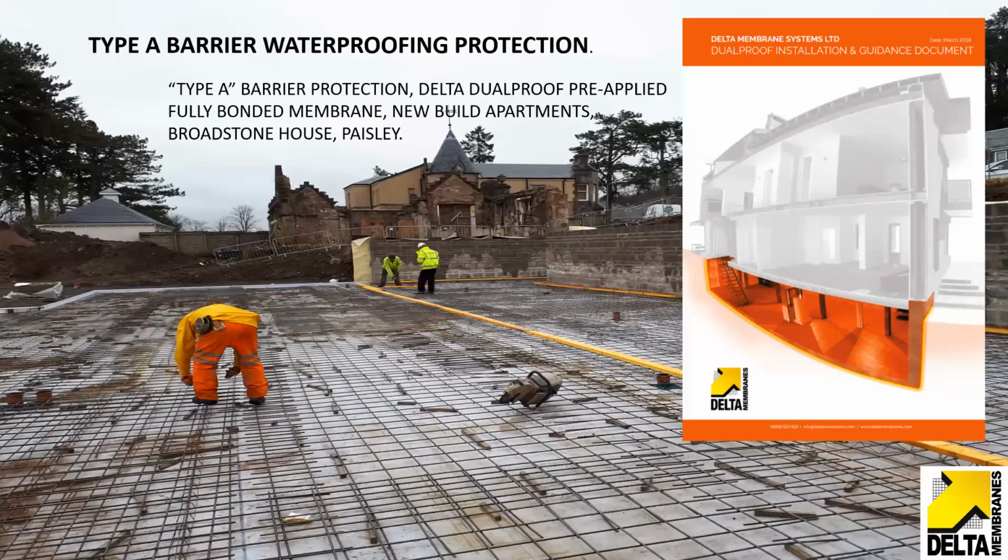We'll come on to different types of waterproofing now. So we've talked about type A, B, and C. Type A, barrier protection. Okay, so this is a membrane, in this case, that's applied under the slab of the basement, before the basement slab is poured. And you can see these guys treading all over this white membrane, putting bits of reinforcement on it. They've probably got stones in the hobnail boots, so what we're getting there is damage, isn't it, potentially? So although the membrane was perfectly installed, these follow-on trades are damaging the membrane.